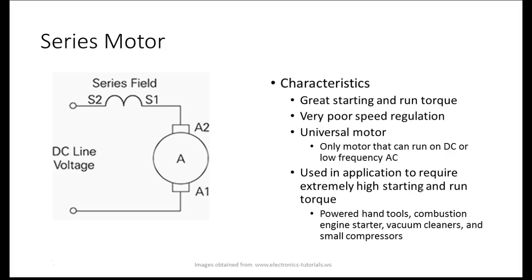We use these in vacuum cleaners. This is what your starter on your car is. It's a series motor. Hand drills use series motors. You ever see it spark in the back? You can really tell those. You can hold them up in your hand and they run real, real fast. As soon as you put them down into a board or something, they slow down, but their torque goes way up.